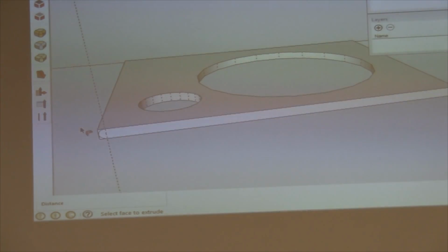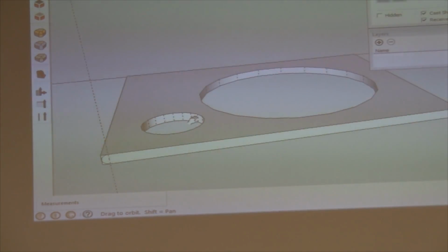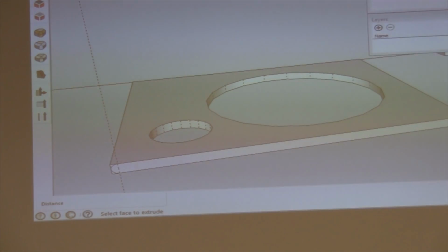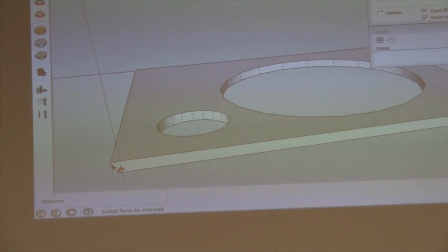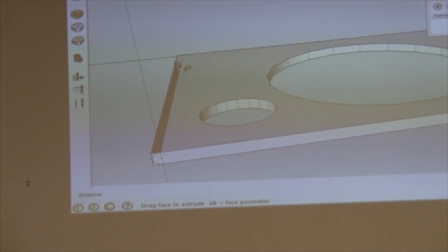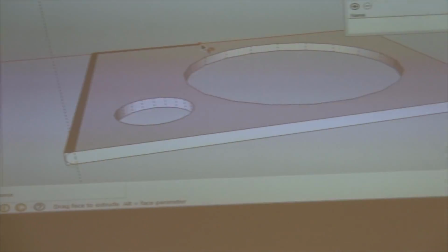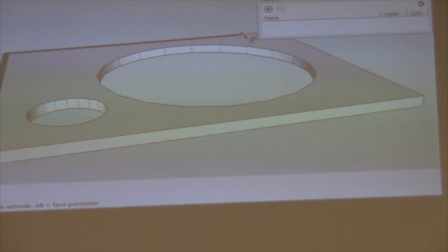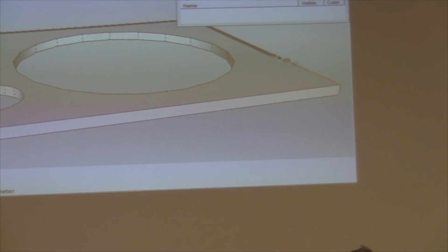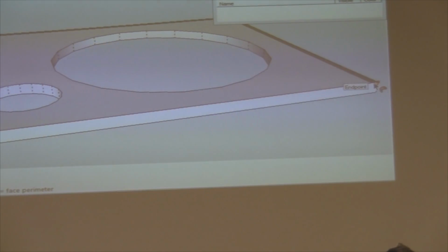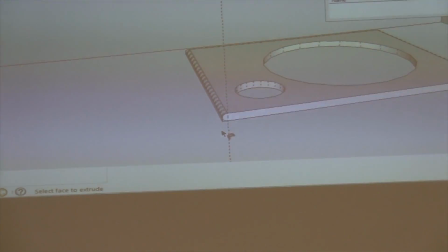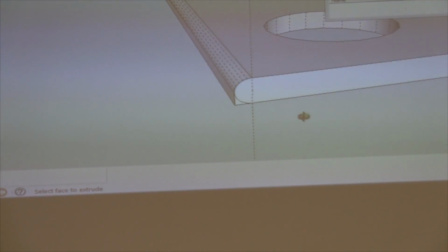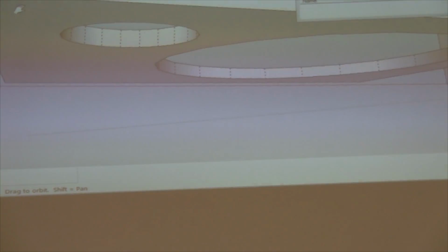So we're going to have to do this basically the manual way by using the Follow Me tool, and then zooming into that surface and then dragging along the profile line that you want it to be cut. It's like taking a router to the edges that you want, is all it's really doing. And then you end up with that.